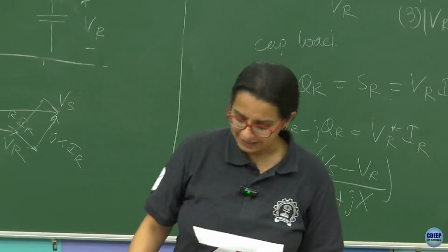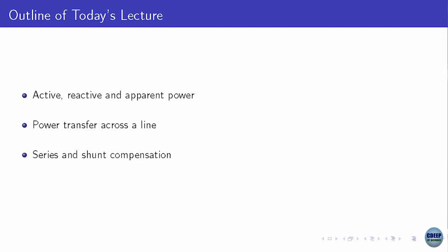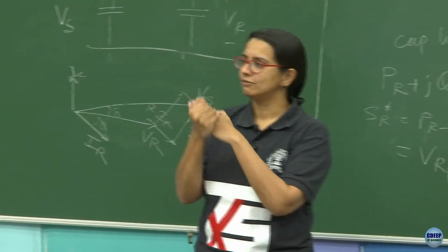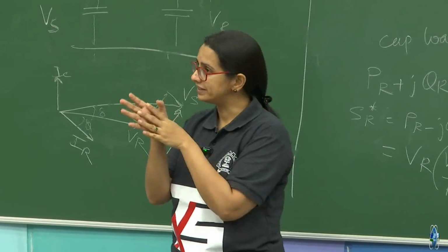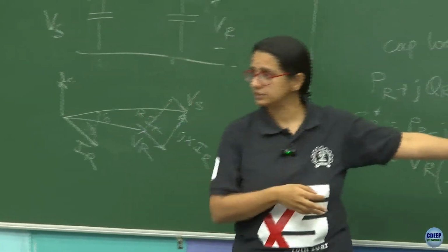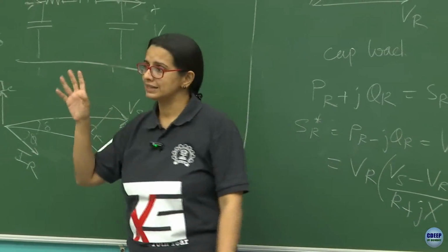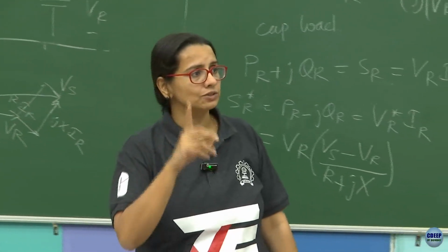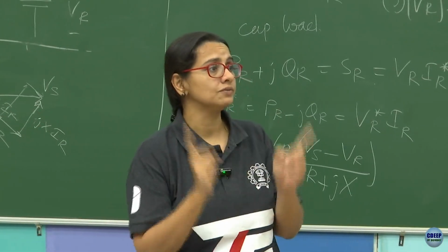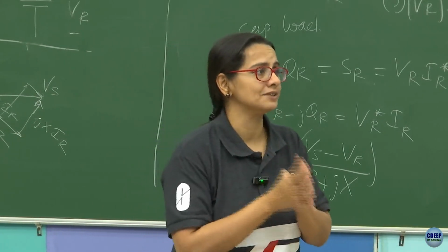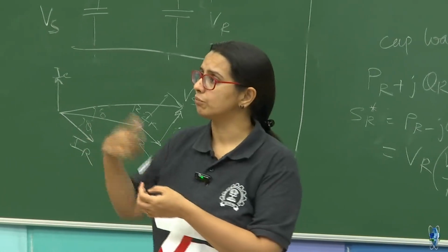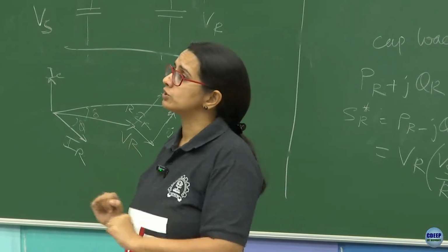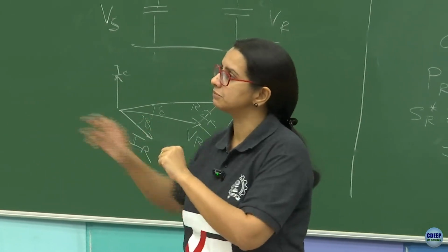So very quickly, let's recap. What did we cover? Hopefully now you're a little bit wiser about active power, reactive power. Hopefully now you know that power transfer across a transmission line is going to be a function of the voltages, but also a function of the phase difference, and more primarily governed by the phase difference. Please remember this, we'll revisit this when we go to other more complicated calculations of how much more power we can push given some trades and so on.